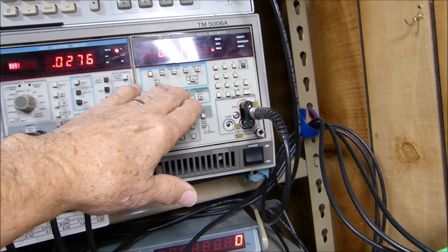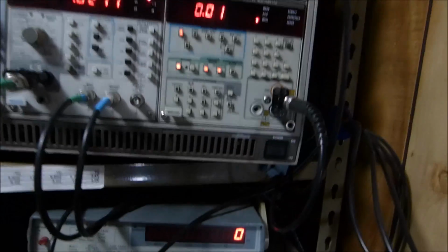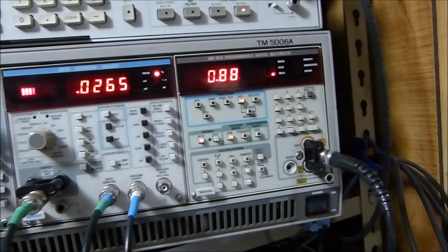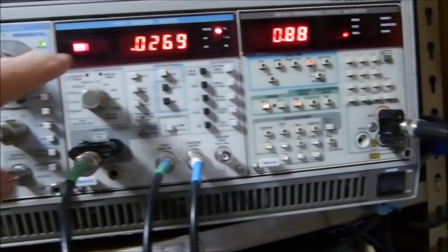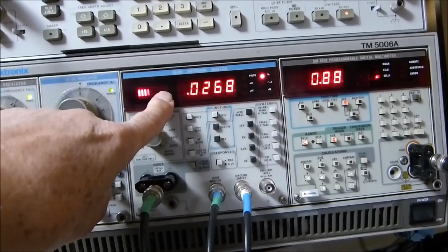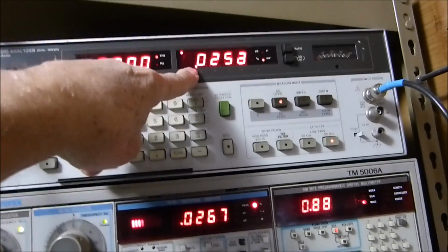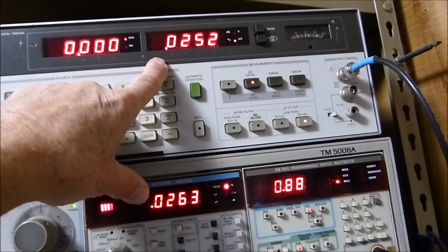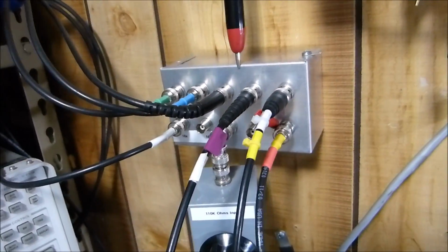The only one that it requires the actual 5000 module mainframe, darn it, is this fellow right here. A beautiful device, voltmeter. This is called a DM5010. This is called an AA501 for audio analyzer. It does THD. I use this thing all the time. I get the same readings up here. As you can see, it's just looking at the noise right now on the line, and it's measuring about the same thing. 0.0263, 0.052, that's the same thing for all practical purposes. It's just measuring the noise out of this breakout box here.